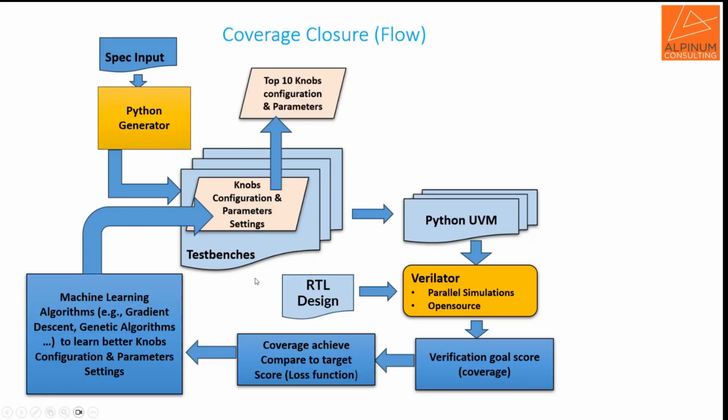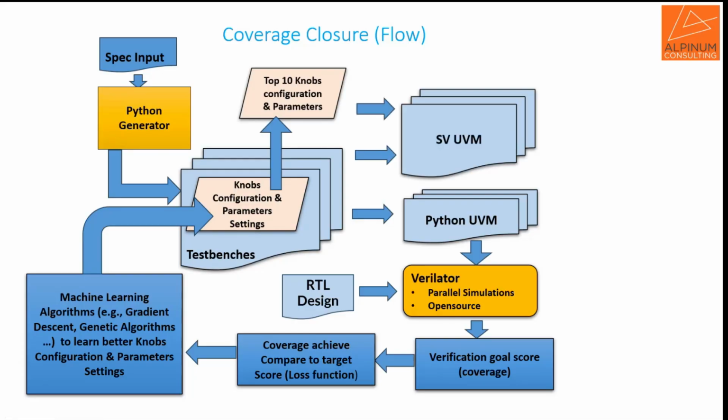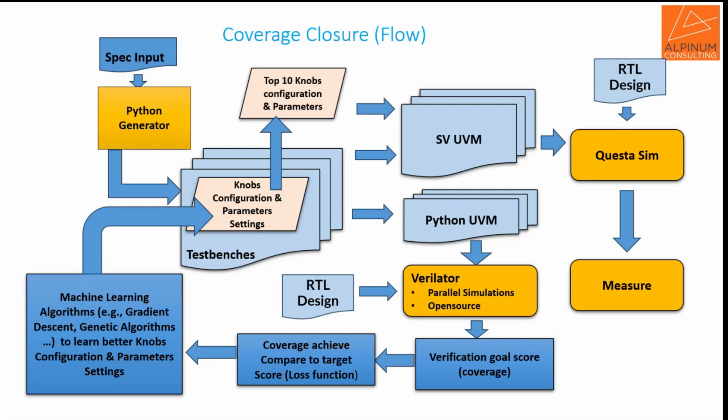So that whole feedback flow is basically going to help in the knobs and configuration for the parameters to this test bench generator. And then we finally have a SystemVerilog UVM test bench that, with the RTL design, we are going to simulate, and we're going to measure our results.